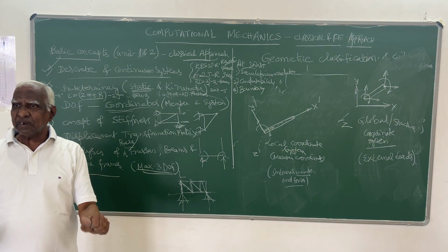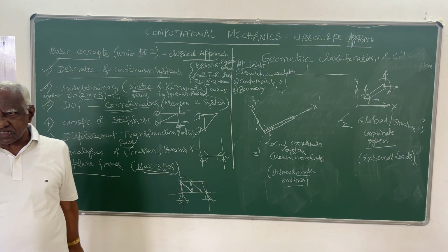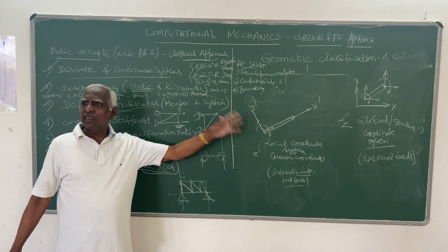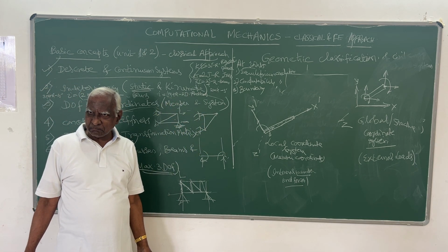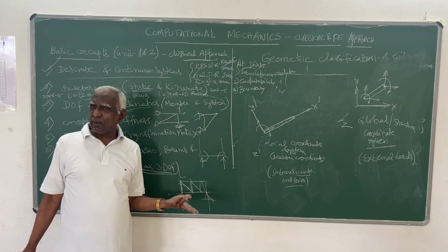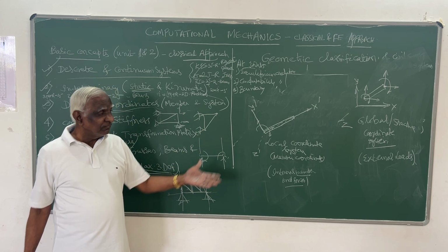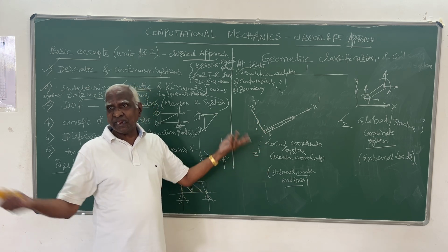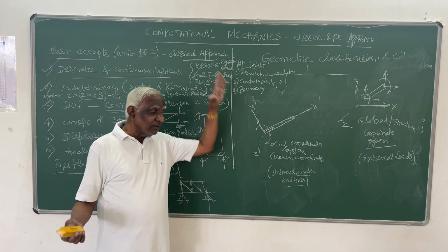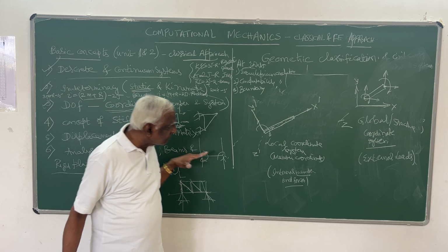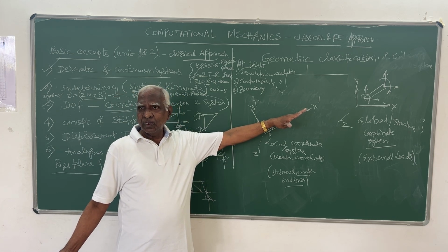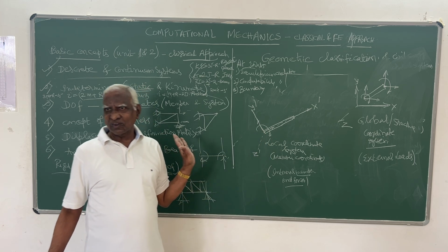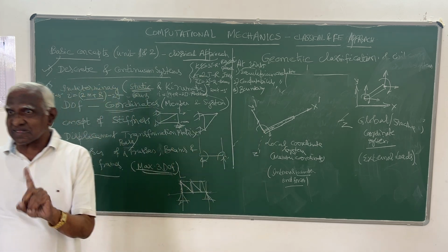But when we are determining the internal resistance, stresses, it has to be invariably in the local coordinate system, because it has to be along the member. We cannot just define it in any direction. It happens actually in any direction, but for analysis purpose, we select it to happen along the axis, along the local coordinate system.